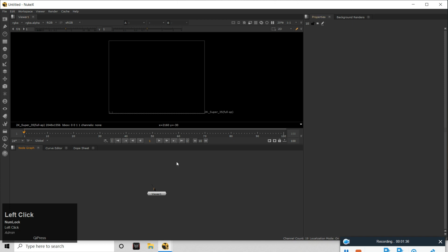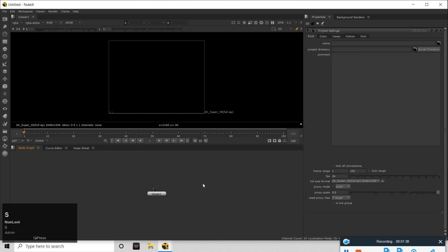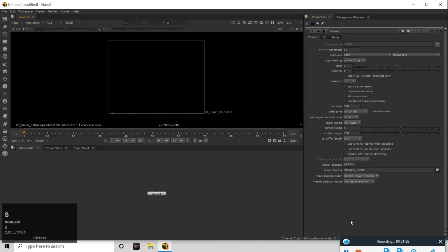If you accidentally close it, you can click here and press S. This 10 here means you can have a maximum of 10 panels. If I give 1 and then click here and press S, I get only 1. I don't get anything down here. Please try to understand.